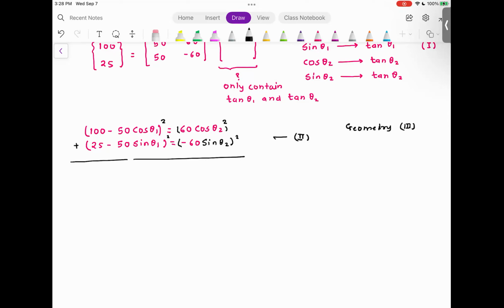Substitute the values of theta 1 to theta 6, and you'll get px, py, pz, roll, pitch, and yaw. However, if you substitute px, py, pz, roll, pitch, and yaw, and try to compute thetas 1 to 6, it will never work. What it means is for a 6 degree of freedom actuator, inverse kinematic solution is not possible for all the cases. So here is the trick.